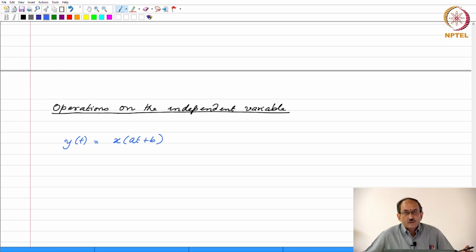If you did this, you are non-linearly compressing the independent axis, and then if you take the Laplace transform of the non-linearly modified signal, that will be the Mellin transform. Alright, so this is not the only kind of transform that exists, but as far as this course is concerned, these are the typical kind of operations that we look at.